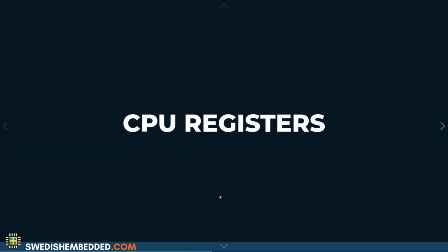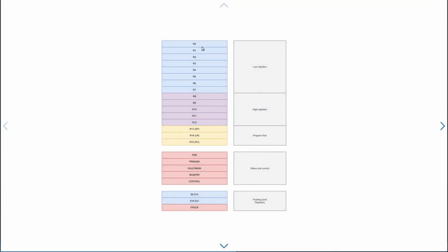So the key concept here is CPU registers. We have a number of registers that the CPU works with, and any intermediate state that results from different instructions that the CPU is executing is modifying one of these registers. Data is loaded from memory into registers, then some operation happens, then the memory is updated with the new value, so the registers are copied to external memory, or to a peripheral, or somewhere else. But the current state of the CPU is represented by these registers.